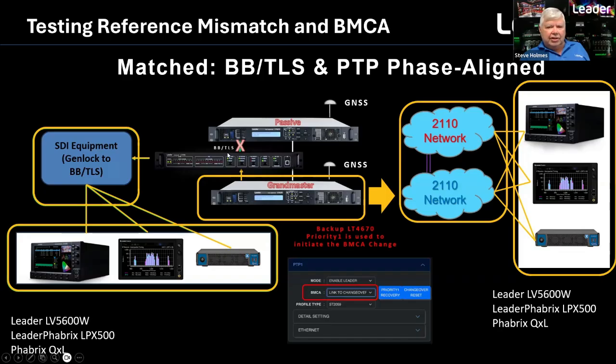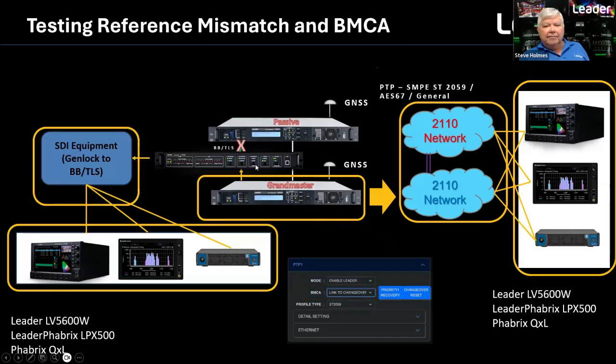It switches, and even if you fix this fault, it's still going to stay switched until the engineer has tested it, walks up and says, switch back. We have the same condition that we can apply to the PTP signal on the second grandmaster and say, even though the primary grandmaster on top up here has fixed itself, do not switch back until I tell you to turn around and switch back.